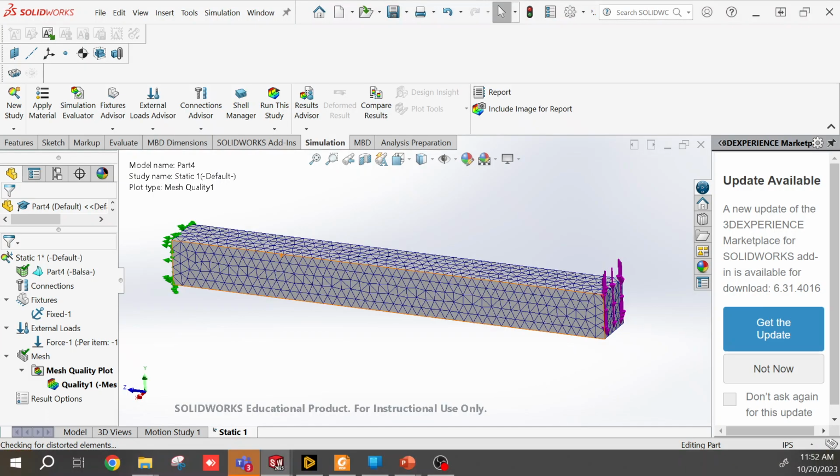So hopefully now SolidWorks is done meshing that. We shall check, and it has. So that's nice, we have our mesh, and we can go under Run this study and click Run. Another dialog box will pop up where it's effectively invoking static equilibrium equations, starting at this boundary condition and propagating it through all of those elements. It has to reach static equilibrium throughout all of them.